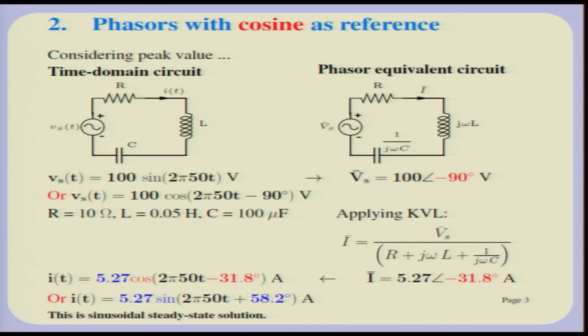So this is about using a common reference. So in the entire circuit here, which is shown here, this is a very small circuit localized using lumped elements, but you can have circuits which are spread over geographical areas, and in that case you should have a common timing reference and also a common, whether you are taking cosine omega t as your angle 0 or sin omega t as angle 0, there should be absolute clarity as far as that is concerned.